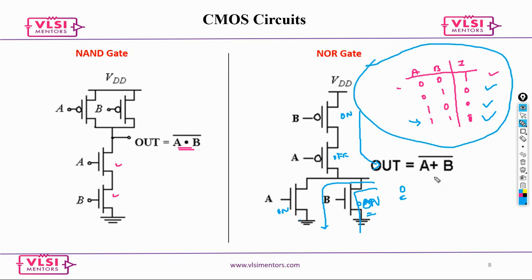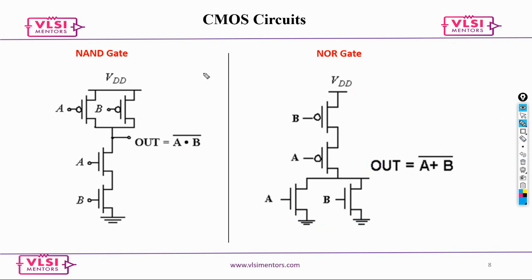Now the question is, I'm not sure if you guys remember, I asked you during the digital course: is NAND bigger in terms of area or is AND bigger in terms of area? If you try to recollect. Usually in our textbook, we always talk about the AND gate first, and then you add an inverter and we call it a NAND gate. So tell me which one is going to be higher in terms of area.